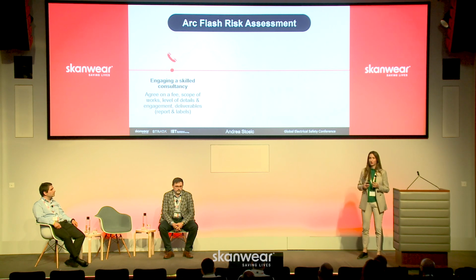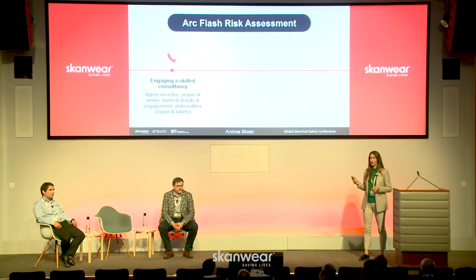This will make your life so much easier. You'll need to agree on the fee, of course, on the scope, level of details, level of engagement, and the IEEE 1584 can really help you here. You'll also need to agree on the deliverables. This would typically be the report and the labels, sometimes the model as well.